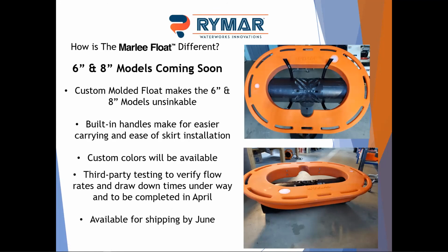We should be testing this one to verify our flow rates for our 6-inch and 8-inch models. We expect our flow rates are going to be substantially higher than most other skimmers. Most skimmers stop around 1 CFS. We're expecting to get at least 1.5 to maybe as much as 2 CFS out of some of these skimmers, just the way the hydraulics are set up. So if you have a really large basin that needed 2, 3, or more skimmers before, you'll be able to reduce that with ours.